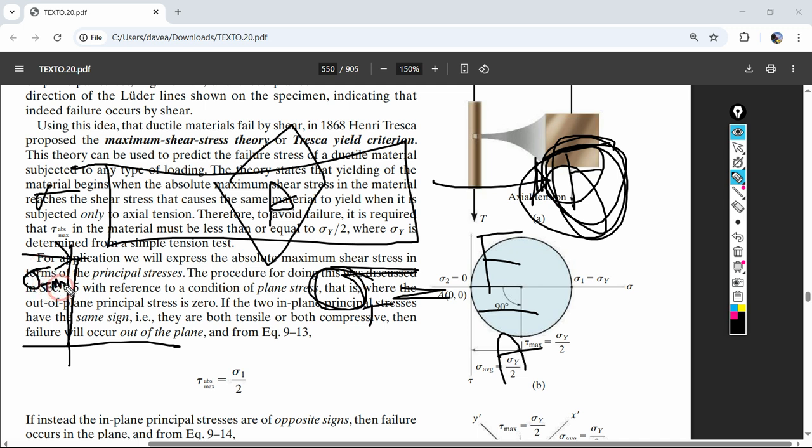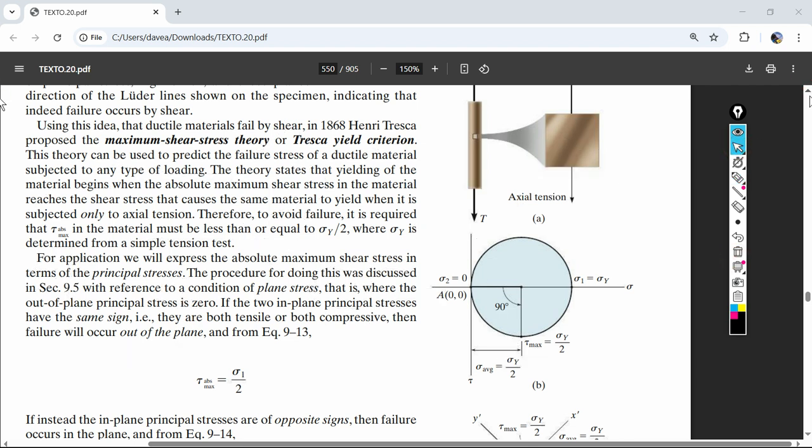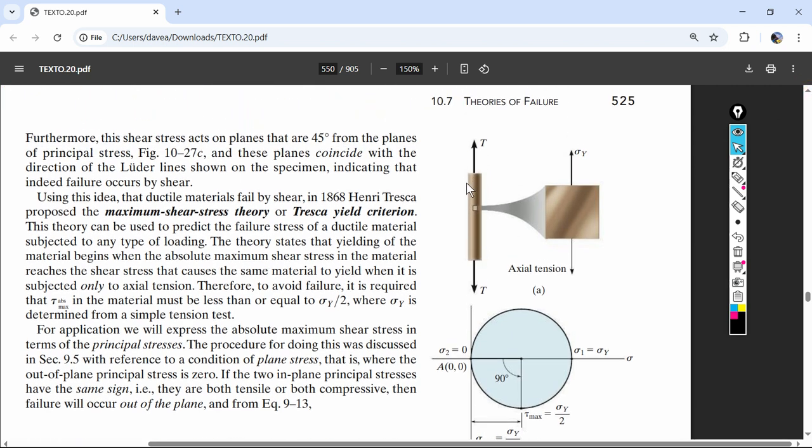That's going to be your max tension, and here we're calling it sigma Y just to show the direction. Most of these tests will be done in a vertical pulling machine. If this is the specimen, they'll pull it vertically. It doesn't matter if you pull it vertically or horizontally, but sigma Y is the term they're using. So that was the first little place where, reading textbooks, I came into a hiccup. It was something I didn't know. So that's the amount of time I wanted to spend on that section, just to figure out what they're saying.